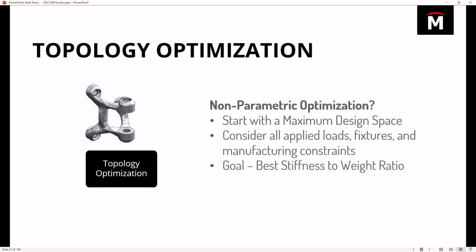But there's another method we could use, which is in Simulation Professional. This is something that came in 3 or 4 years ago, and it's really a benefit of the technology share that SOLIDWORKS Simulation has with Dassault Systems, who owns Abaqus and the Simulia brand and all that. And it's called topology optimization. In this one, I'm not going to tell SOLIDWORKS where I want to remove material and what dimensions I want to exactly control. No, I'm going to give SOLIDWORKS a part that has extra material on it.